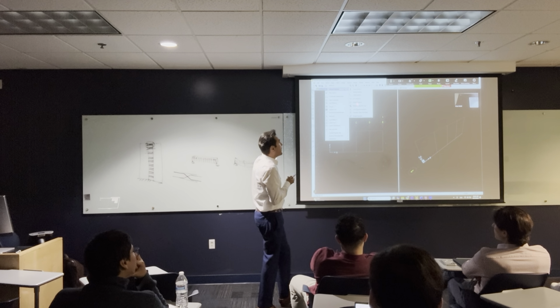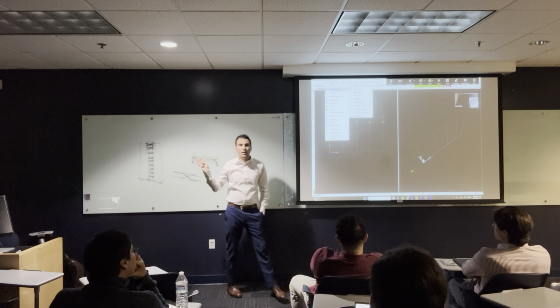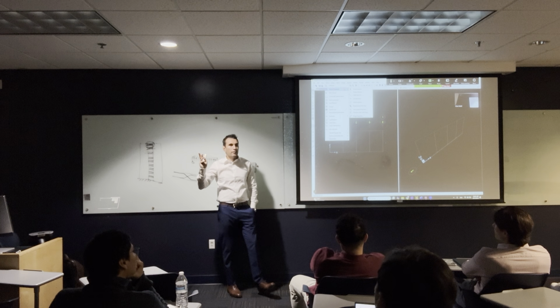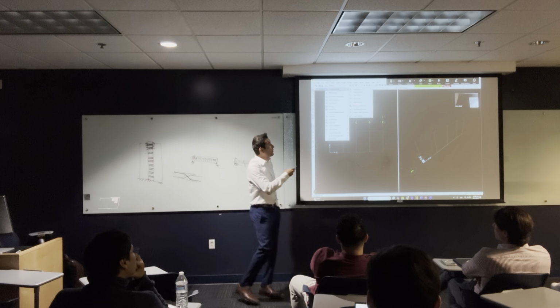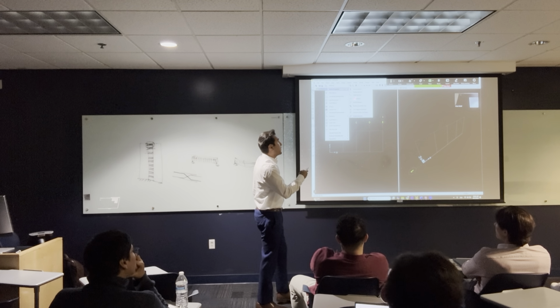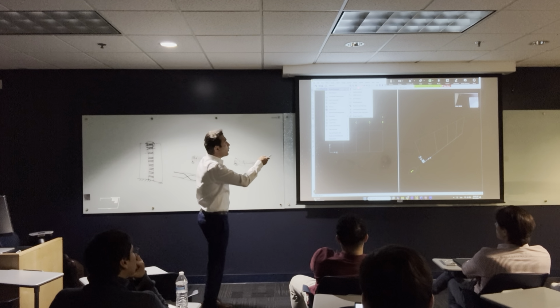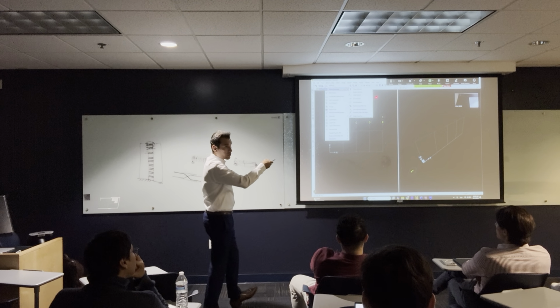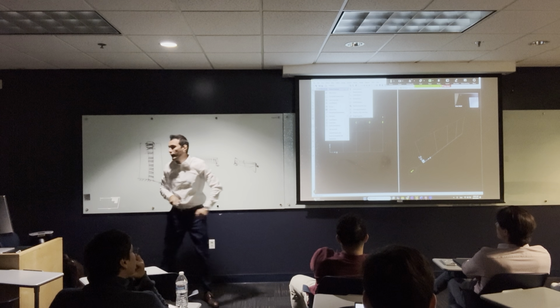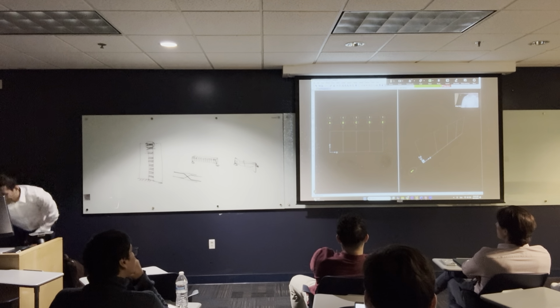And area sections. Area sections are the ones that we kept talking about last week. The plate, the membrane, the shell, all of them are under the area section. And there's something called solid properties. I didn't use it in SAP2000 before. And there's a bunch of other stuff. So we're only interested in frame and area sections for this class. Okay, so let's go to frame sections.